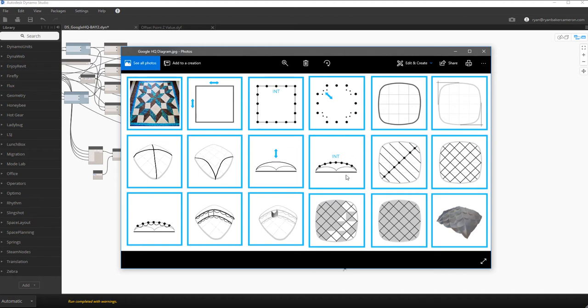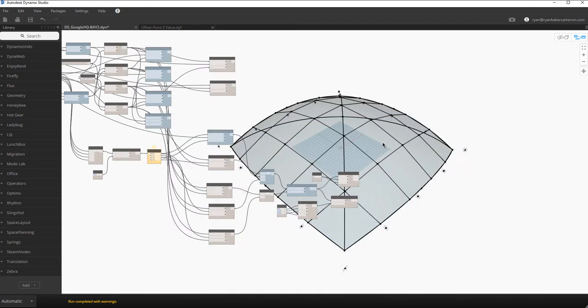So we need to build in some parameters on our curve and then copy that down several times along with the parameters, and really just let the computer automate the lofting in between, providing us a lot of control, and then slowly but surely fill in those lofts. To be perfectly honest, we only have to fill in this little triangle right here, and then basically mirror it 3 other times to get the shape. So it seems like a lot of work, but we really only have to fill in just a few of these really, and then mirror them all the way around.